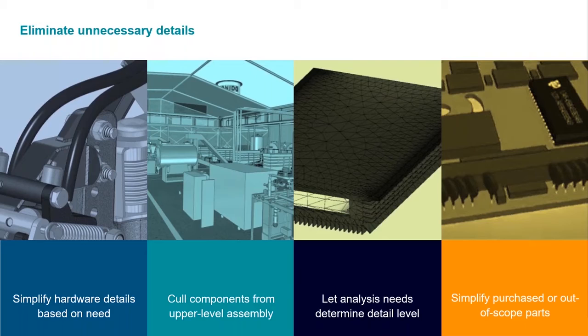In many cases, modeling just the head of the screw or the bolt is enough representation of a standard part in a large assembly. Now, best-in-class CAD systems like Solid Edge also support occurrence property options, which allow us to call components such as bolts and fasteners from those upper-level assembly models. We can also consider doing analysis on our models and those needs when determining how much detail to show. Unless you are the bolt manufacturer, you likely don't need to do in-depth stress analysis on your bolts in your assembly. So very few companies really need to represent these parts with a high level of detail.